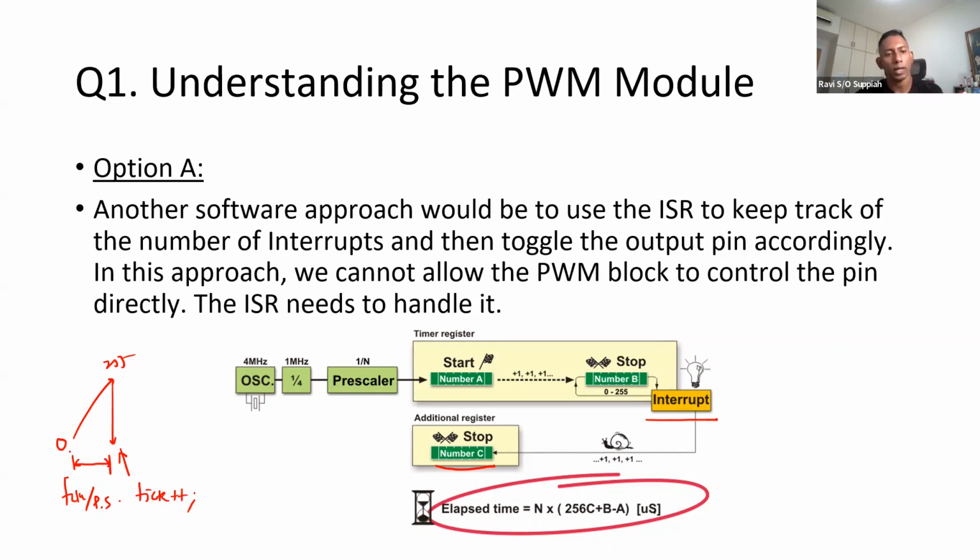All right, so assuming that I want, let's say, a 5-second interrupt, and this count here, the maximum I can stretch it is maybe 1 second. That means I just need to wait for tick to go up to show that it's 5 seconds, that 5 ticks have incremented. Then I know that I have fulfilled the timing gap that I want.